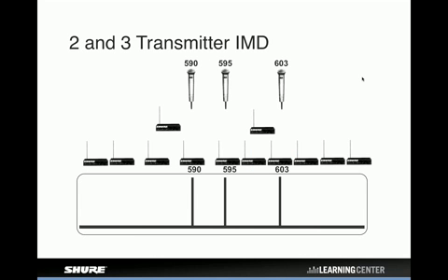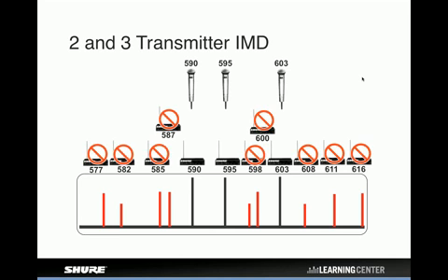Again, our 3 transmitters, these work totally fine together, but by just having 3 transmitters on the air, there is 9 additional frequencies that need to be avoided in order to make sure that this system is going to work properly. And again, these are all mathematically predictable. We can know where those frequencies are. We have software programs that do such a thing, so we'd be able to pick our 4th frequency successfully.